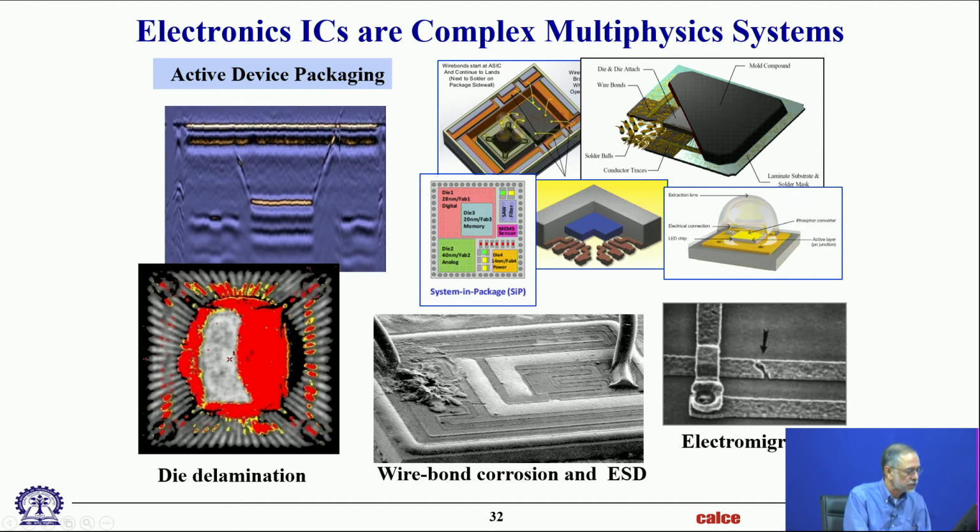You get an electrical overstress. So this is completely blown off, meaning melted because the current density got too high due to that complex interaction: corrosion, fatigue, and then electrical overstress. So it's a sequence of events that cause that failure.